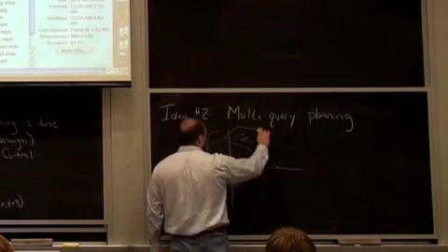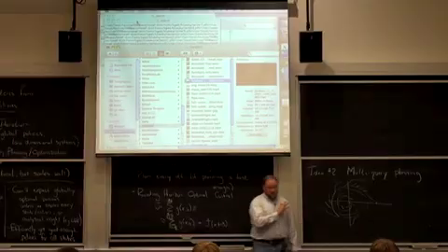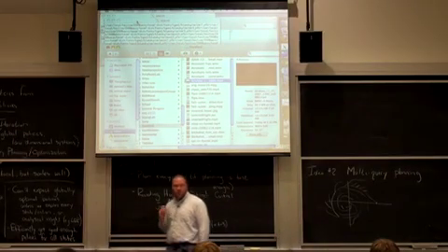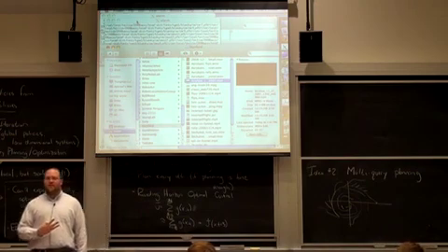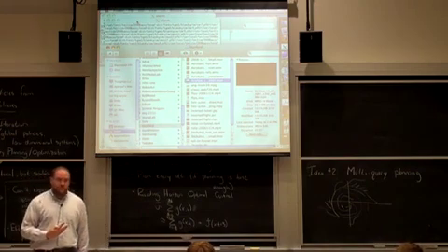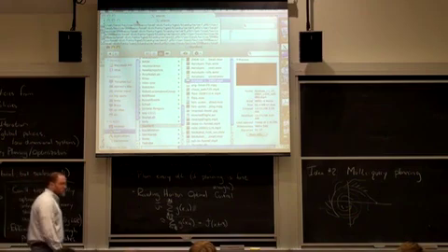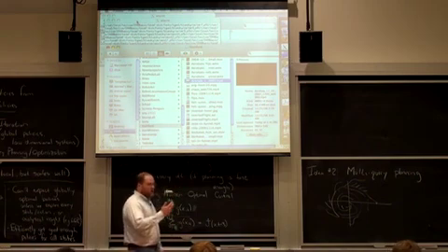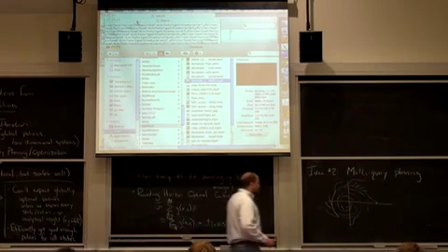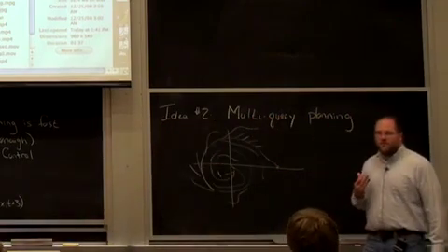And what you have is sort of a web. In this case it's a tree. If you run the RRT once, you have a tree of feasible trajectories that you could execute on the real robot, right? It happens that one of them got me from the start to the goal in my initial problem formulation. Okay, but instead of throwing all that computation out and just keeping the nominal trajectory, I might as well store it.